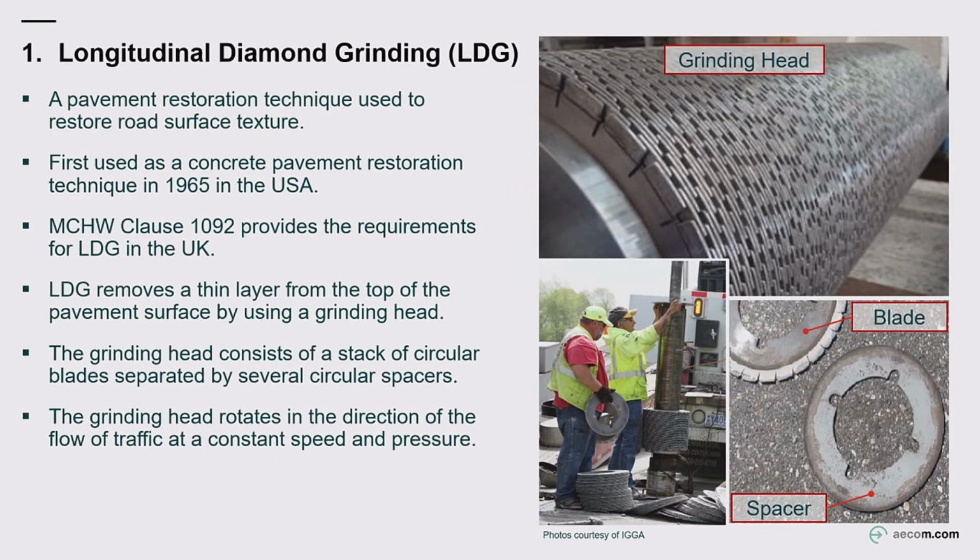As for LDG, as Ian has already mentioned, it's a pavement restoration technique that we use for either asphalt or concrete. We are focusing our research on concrete. We have a grinding head, a blade, and some spacers, and they end up stacking them together into a drum or a shaft, and then they rotate this in the direction of the traffic flow at a constant speed and pressure.